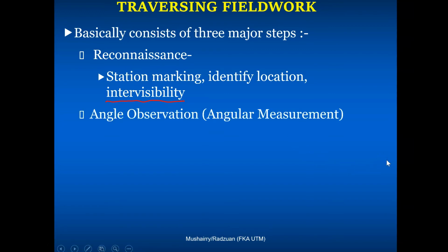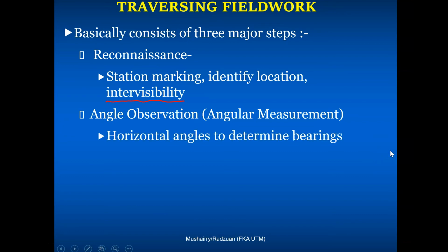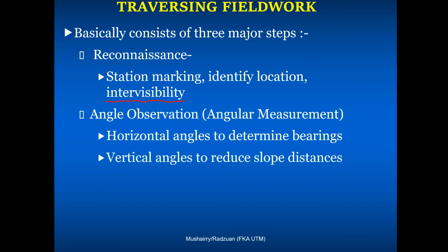Then angle observation. Okay, you measure the angle using the total station, and you measure horizontal angles to determine the bearings, and don't forget to measure the vertical angle as well.